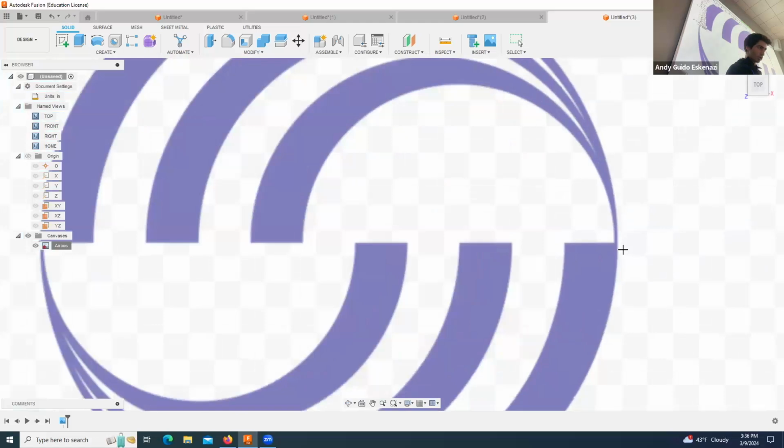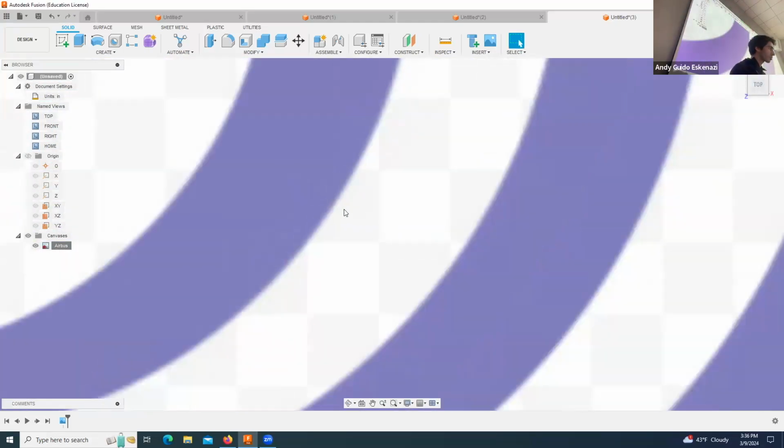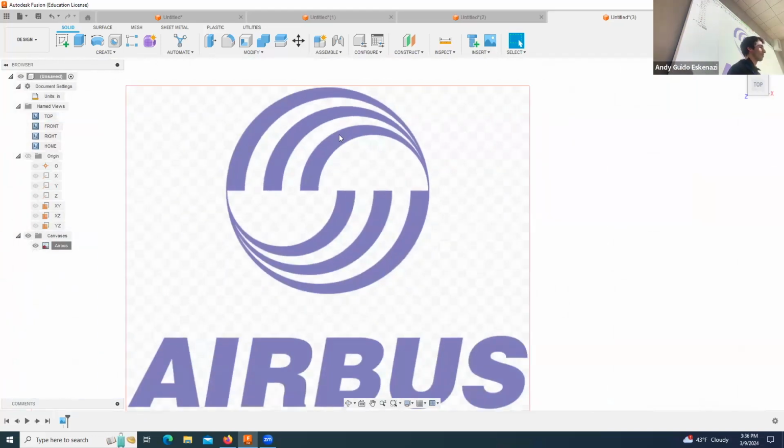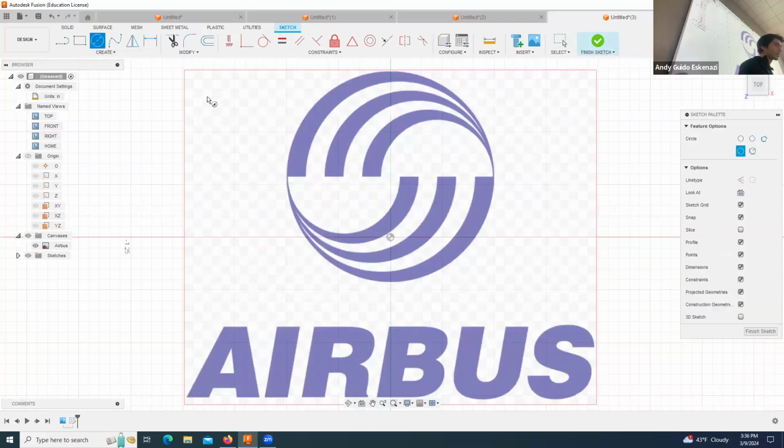I click on that point, click on this point. I want to make that 1 inch. There you go. You can do that with whatever logo you have. Say you're doing one that doesn't have a circle around it, make it slightly smaller. That way you can then do a circle around it that is 1 inch. If you have a chess piece, make it like 0.8 inches. That being said, I'm going to start doing stuff in here real quick. I'll make the three points.